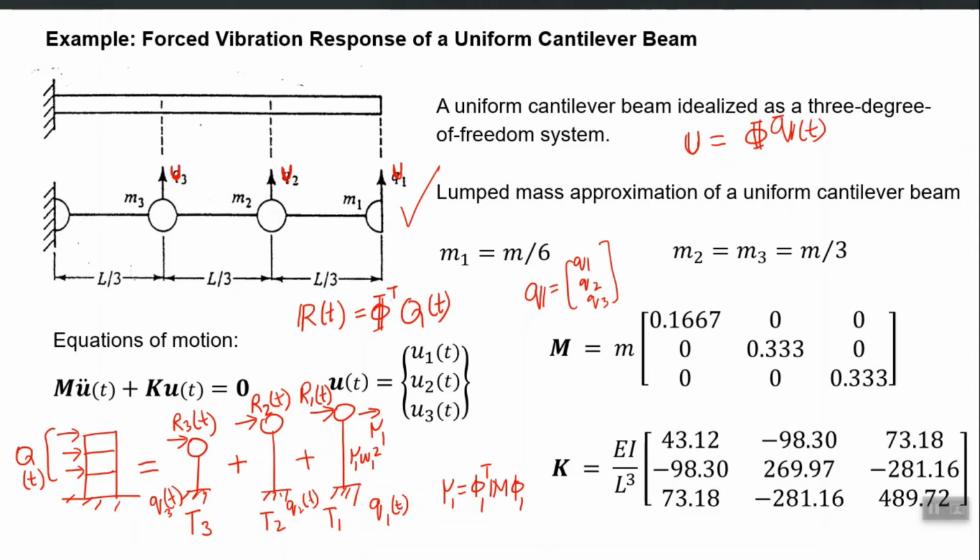So it is just like a shear building, but rotated in a horizontal manner. It can be treated as a shear building. So the u of t vector, which is u1, u2, u3, holds the 3 displacements of these 3 masses. And first let us treat the case of undamped free vibration response. So m u double dot plus k u is equal to a null vector.